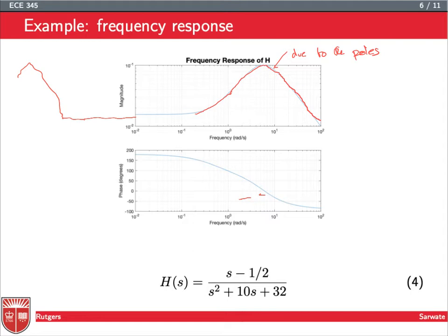But as we'll see, in negative frequencies, if you think about it, a cosine is made up of a positive frequency and a negative frequency. If you think about e to the j omega plus e to the minus j omega, cosine omega t is equal to 1/2 e to the j omega t, so that's at a frequency omega, plus 1/2 e to the minus j omega t.